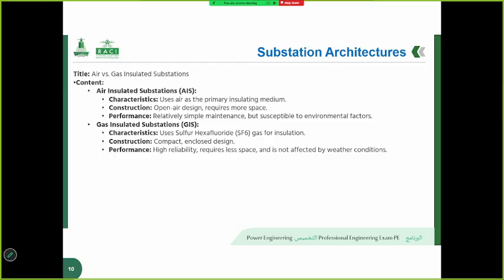AIS has a long history of reliable operation, and it is relatively easy to maintain due to the accessible nature of its components. However, its performance can be affected by environmental factors such as pollution, humidity, and weather conditions, which can lead to flashover or insulation degradation.